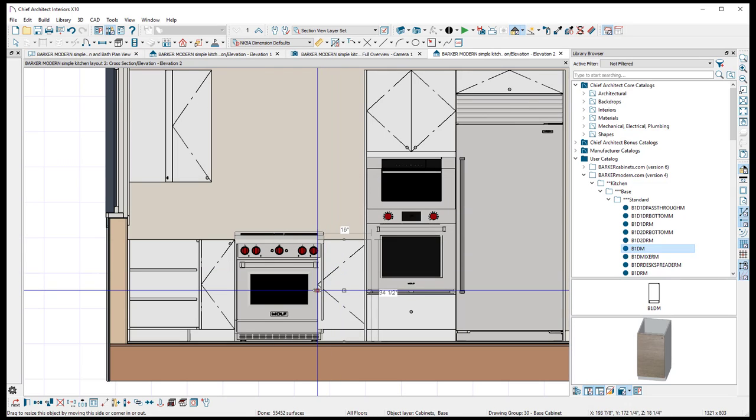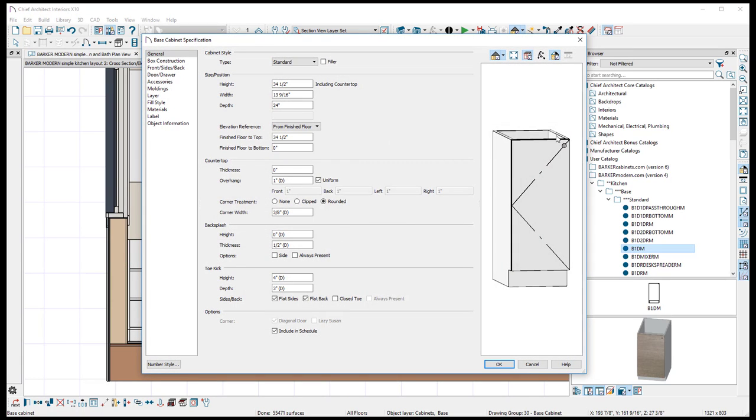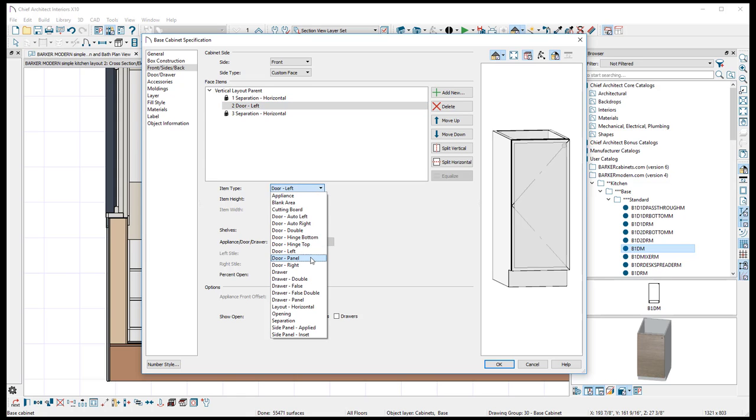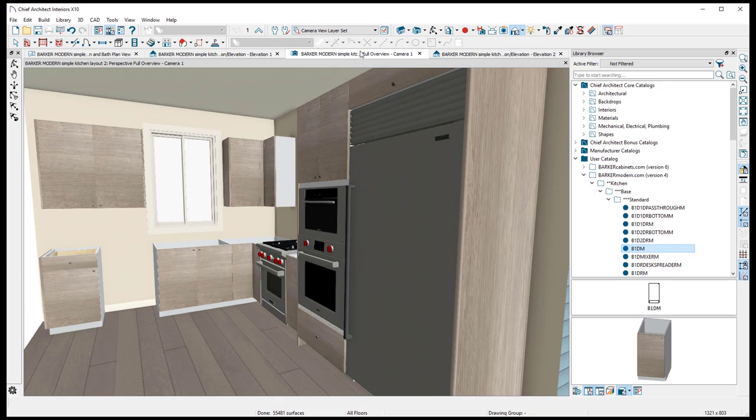It's going to overlap the cabinets. It's warning you, saying, look, you got a cabinet inside of another cabinet. It's not physically possible. Unless you can create black holes or something. Put it in another dimension. All right, you got the door on this thing. If you want to have it hinged the other side, all you got to do is go over here instead of door left, go to door right. Say okay. Now your perspective view looks great.